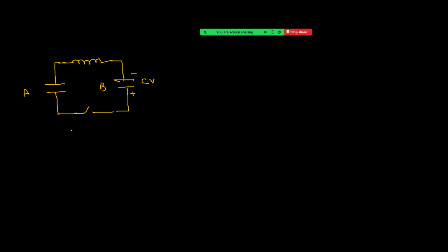When current in the circuit is maximum, charge on the capacitors is the same. First thing, current maximum. Then see what happens. Current maximum means di by dt will be zero, first thing. Therefore, the EMF induced across the inductor, that is L into di by dt, is zero, right? The same logic we have taken in the last lecture also. That means across the inductor there is no EMF induced. Therefore, across this capacitor and across this, both have the same potential difference.